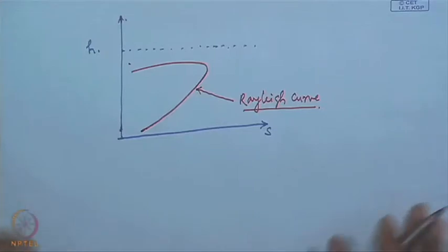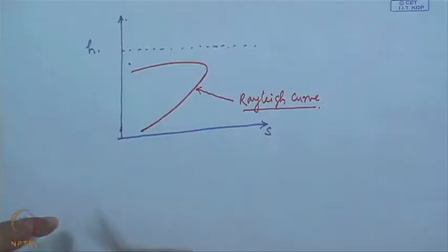Now, for continuous changes in duct, as we mentioned earlier, there are most commonly these three factors: heating or cooling of the flow, or wall friction, or change in area, which in essence is isentropic flow. So, all can be represented here.